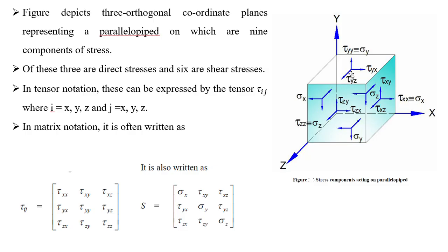If you take all these parameters, 3 faces of the body, top and side faces, these faces indicate in total how many components? 3 normal components and another 6 off-diagonal upper and lower triangular components. Okay, normal components and shear components of the stresses. You can see 6 shear stress components and 3 normal stress components. Total overall we have 9 stress components, whereas 3 are the direct stress components and 6 are the shear stress components.